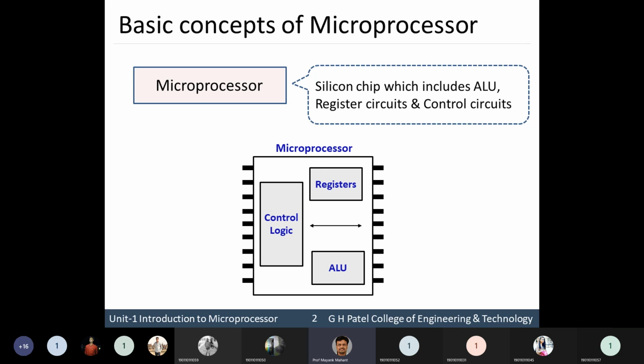Nowadays we have a concept of direct memory access. If I want to process a small amount of data in memory, I can do that directly. If I want to store data coming from an external peripheral directly into the memory, previously it had to first go into the microprocessor, which would then allot the memory place where it was to be stored. But we can bypass this to reduce the burden on the CPU, and we have the concept of DMA, a direct memory access control. But in the case of the 8085 we do not have that.